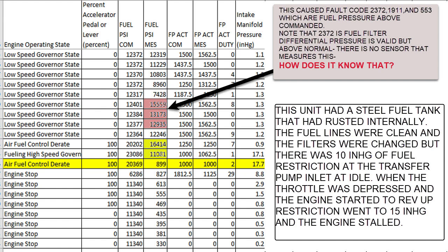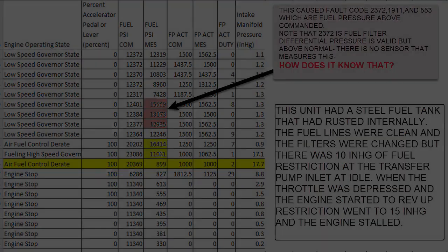Now, look to the bottom. That's what was wrong. They had checked the fuel filter, the fuel lines, looked up in the fuel head at the job. Everything looked good. It had a 90-degree inlet fitting. They took the fitting out, and in the small passage in there, it was packed solid with rust. And so the mechanic came into my office after he found that, and he's got a smile on his face, and he looks at me and he says, I looked every place on that whole fuel system for a problem. And I said, except